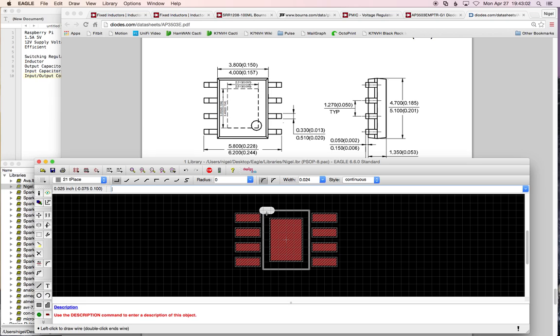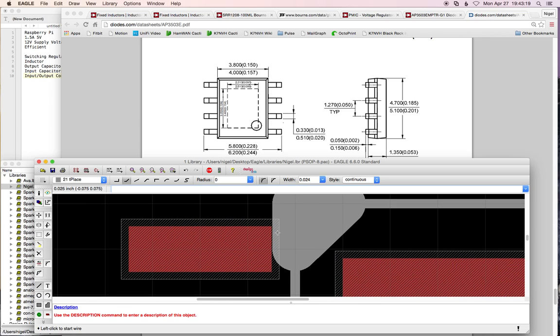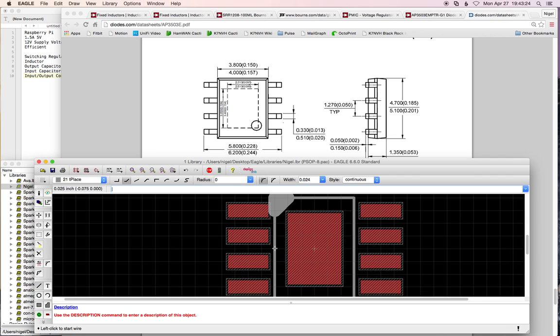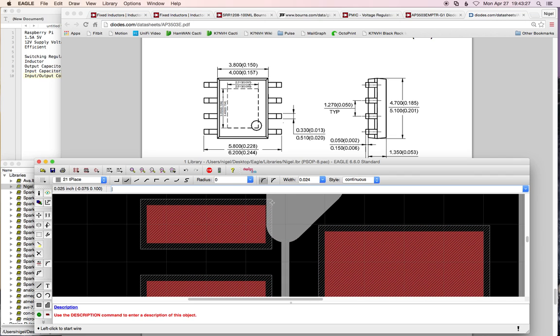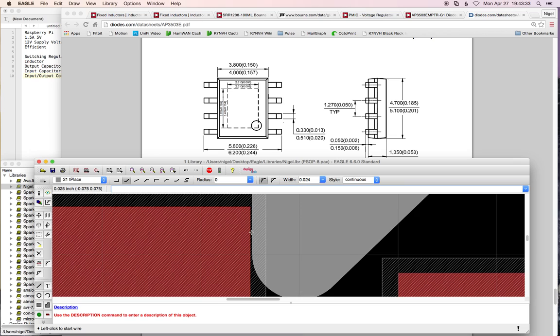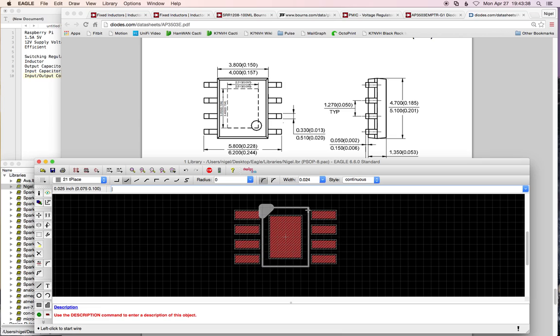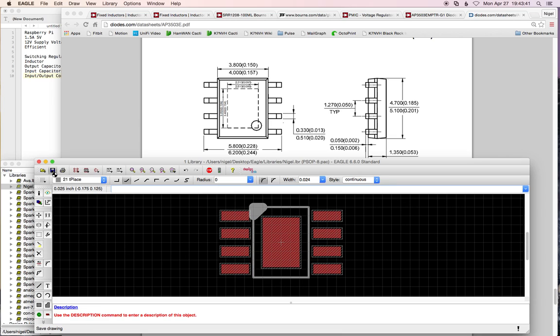And that'll help, I'll probably make this a triangle. And so that'll be my pin 1 reference, is that you'll see a big thick chunk there in the silk screen. And you'll note that, over here, the silk screen gets close to the pad. I don't usually worry about that. The manufacturer of the board itself will pull the silk screen back from the pad. And even if they didn't, the overlap is minimal. I wouldn't expect it to be any sort of issue in terms of soldering this thing. So I'm pretty okay with that.